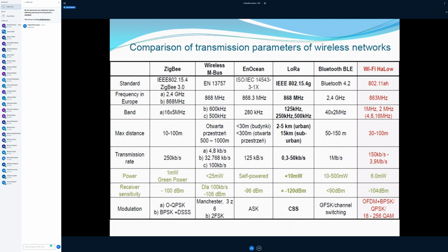Also, the sensitivity. I told you at the beginning of our meeting that when we talk about signals, we do not use linear units. We use decibels. And decibels are a logarithmic unit. You have a reference value, you divide your measurement by this reference value, you calculate the logarithm, and then you multiply it by 20 or by 10.